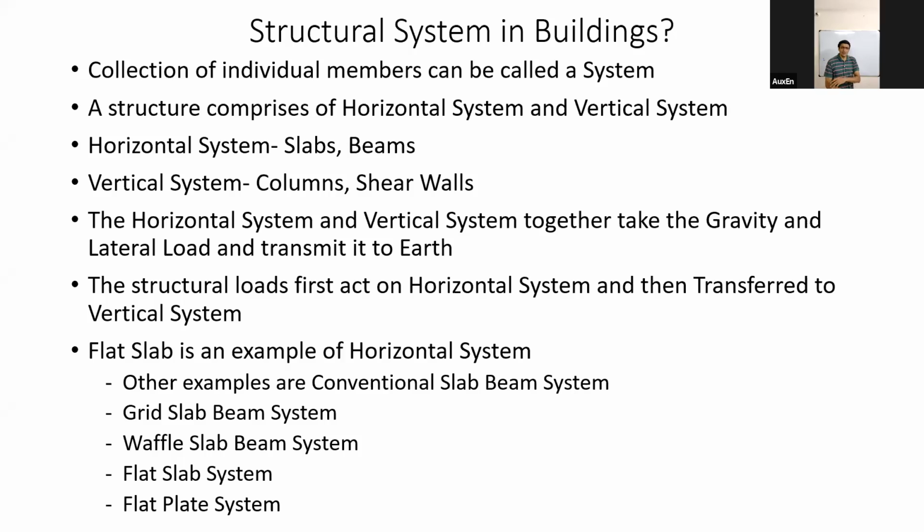In all of these systems, you can add pre-stressing. I will not say pre-stressing is a separate system in itself. It can just be a component of all these systems. Any of the horizontal systems can be strengthened by providing pre-stressing. So I'm not putting pre-stressing in another column as such. It is just an added element for all these horizontal systems. Okay, so what were the conventional examples that we discussed?